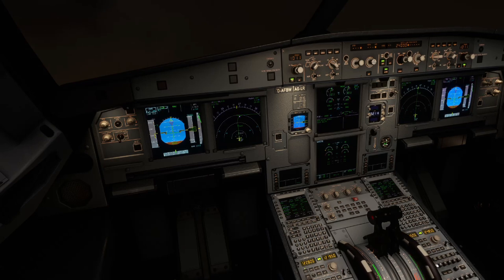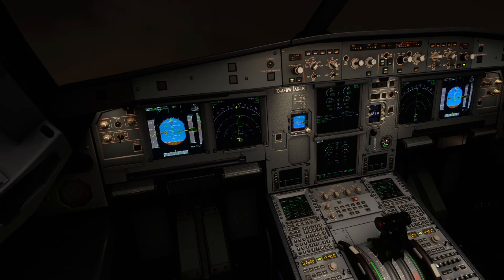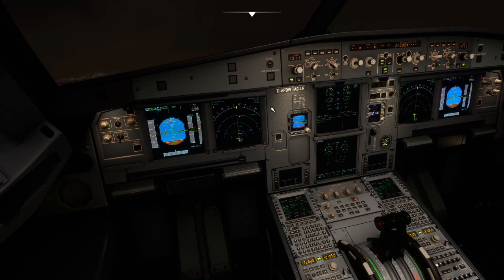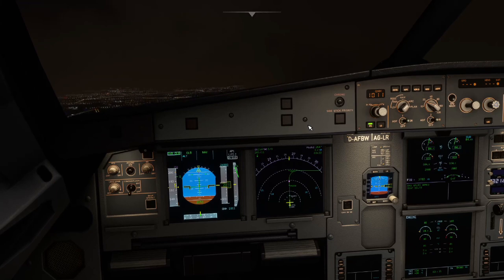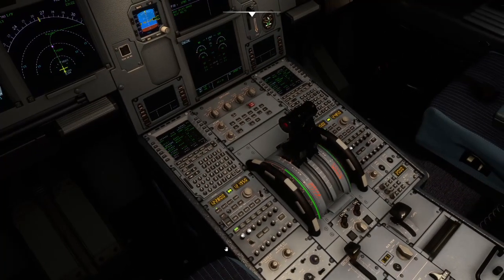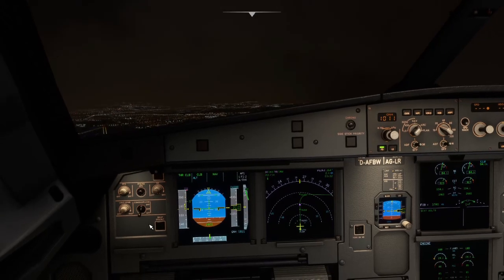There you go, there's through 1500. Throttles back to the climb detent. Starts the acceleration program. You can see it's backed up to 50. Good to disarm the ground spoilers at this point if you're not too busy.